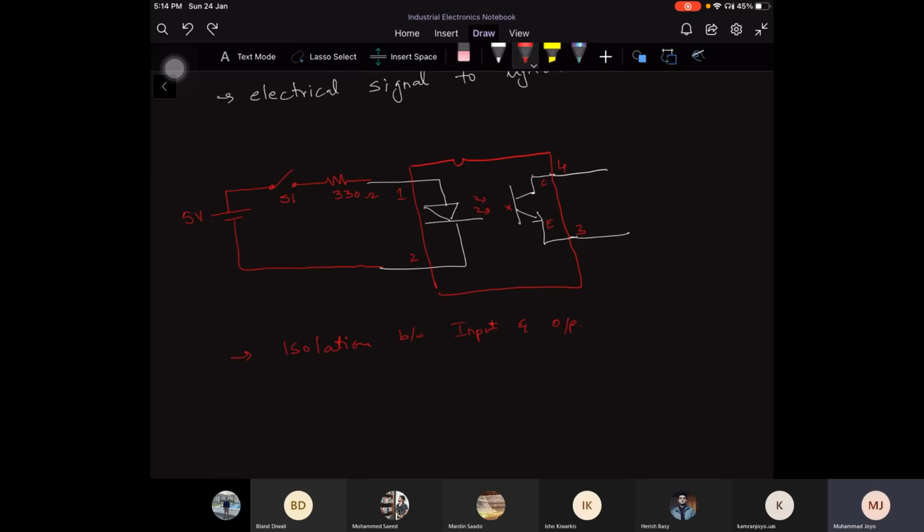You cannot attach a relay with a motor if you are controlling its speed, because controlling the speed requires a PWM signal, not high or low logic. So when you provide a PWM for a motor, then you need to attach an optocoupler over there, so it can switch on high frequencies as well. I hope you can understand the idea.